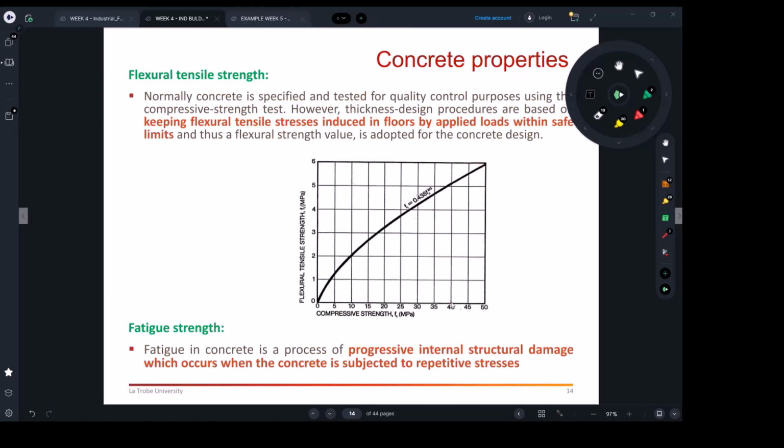And as I said to you, if that concrete takes 40 MPa, a lot of compression, it can take only 5 in tension. And sometimes the tension stops under 5, sometimes goes above 5. If it's under 5, then you don't need additional steel to resist flexure. You just need it for shrinkage. If it's above 5, then the steel needs to be increased. Okay, so that's basically the knowledge you would need to know as a construction engineer. But all the calculations and numbers will really come from the engineers. But you just need to know what you're doing.